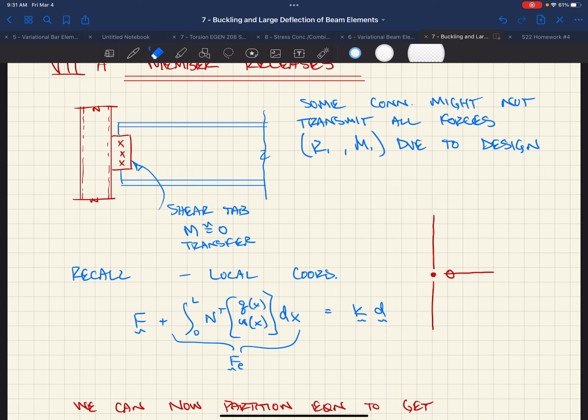And as I mentioned earlier in this class, you might have forces that are coming vertically, and then they might hit that rigid diaphragm, a super deep beam, right? It's super stiff. It might pull load out of that frame, even though that frame is continuous to the ground level. It might pull it out of that frame and bring it to a brace frame next to it that's even stiffer, which you would never capture if you did it by hand, right?